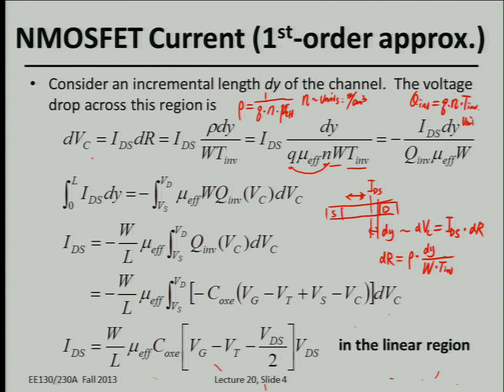with the units of Coulomb per area, per centimeter square. That tells us what areal inversion charge concentration per area you're going to have in the MOSFET channel at a given gate bias, as well as some other conditions. In that case, we got this relationship here. And we may also shift the denominator to the left and perform the integration on both sides, starting from the source side of the channel to the drain side of the channel.